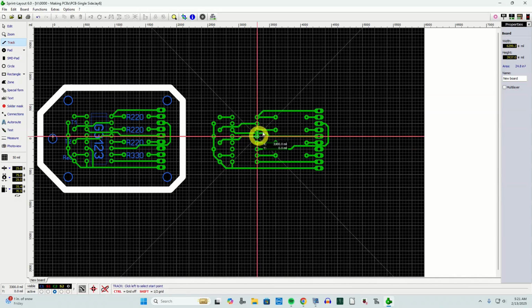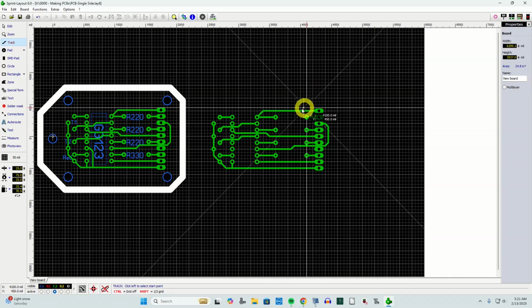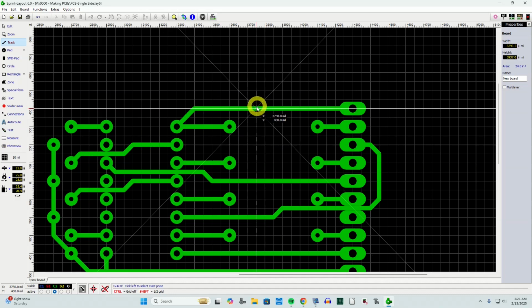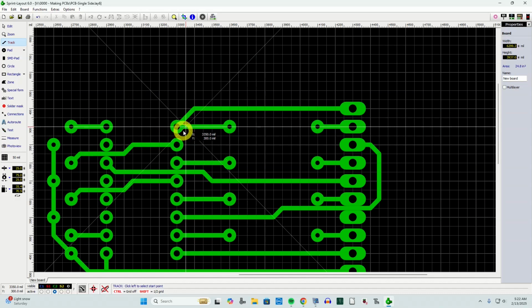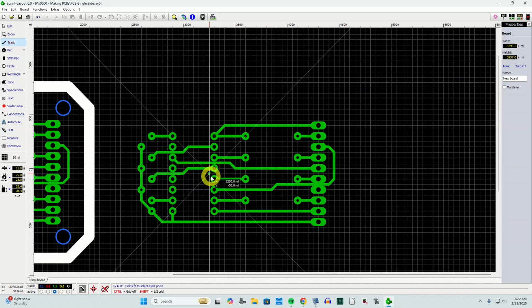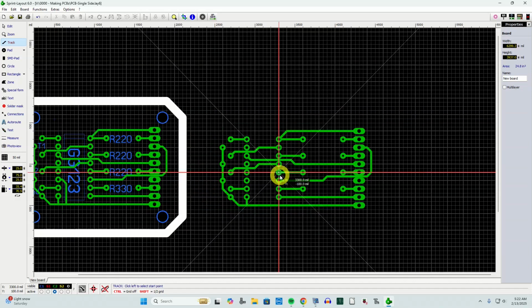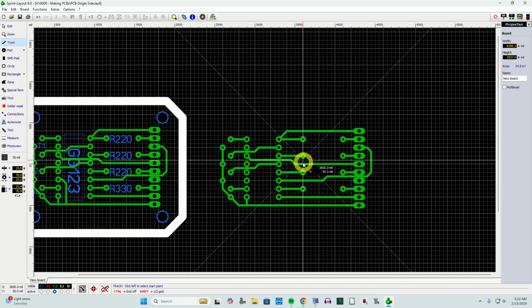At this point, I've got the bottom copper layer all set for the isolation milling. And this is actually where the name comes from. We're going to isolate all these traces by milling a groove in the material around them. And that is specifically isolation milling. But incorporating this with all the other processes, we still generically refer to it as isolation milling.